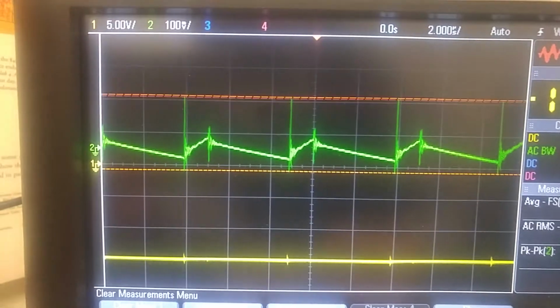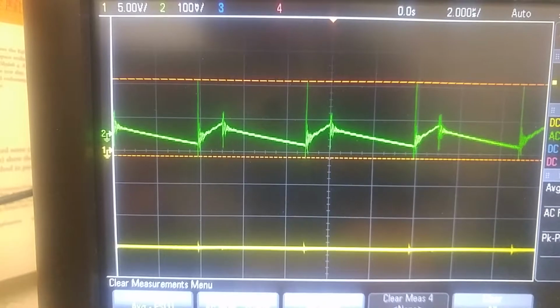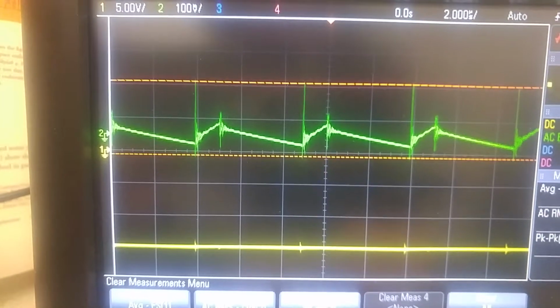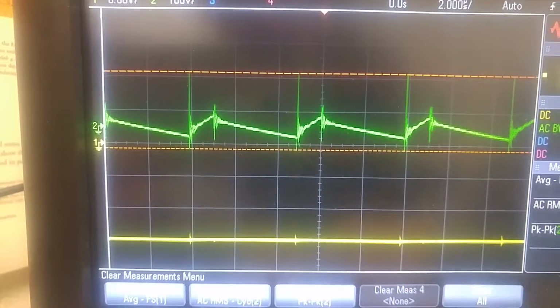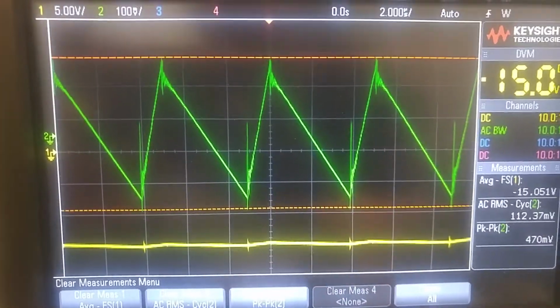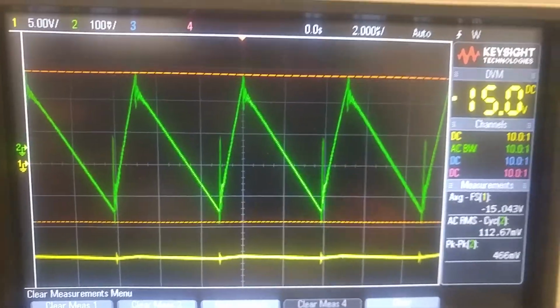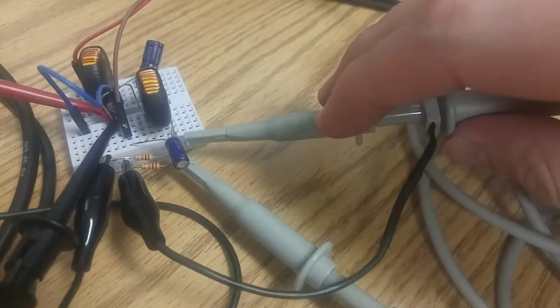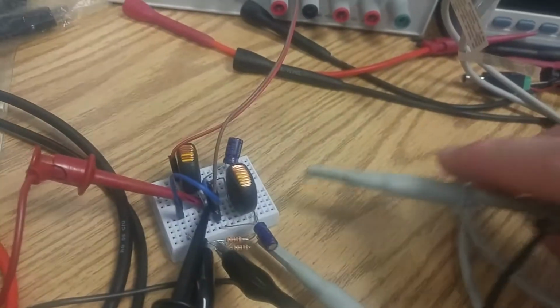I need more fingers. See how the triangle part is now between a division? Well, that division is 100 millivolts peak to peak. I made both specifications. Those spikes are really annoying. I don't like those spikes. Well, actually, it's a measurement thing. We know that this is a big inductor, and we have big waveforms, so let's get rid of those.